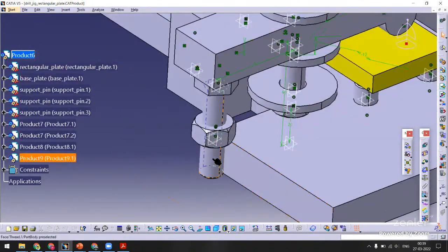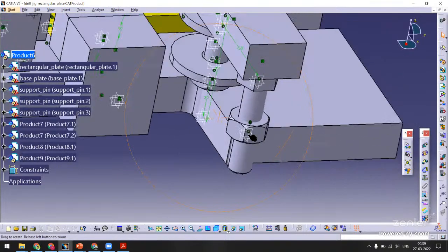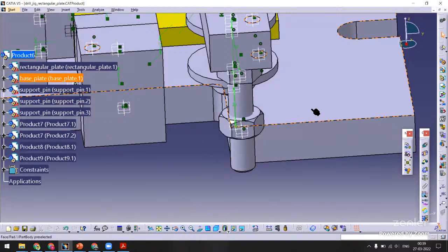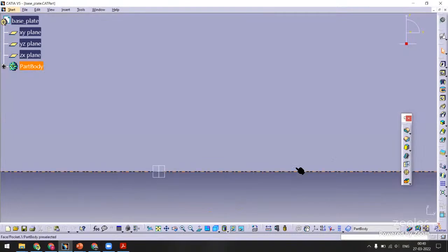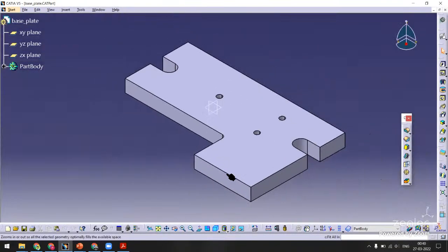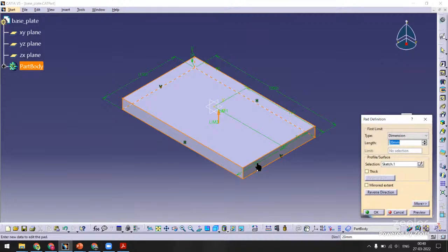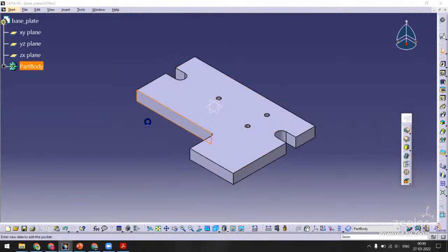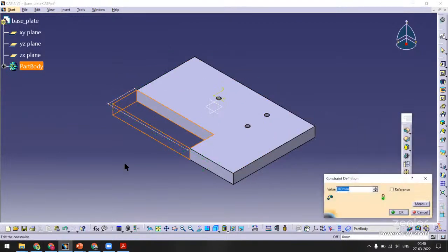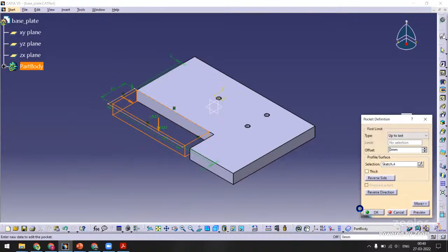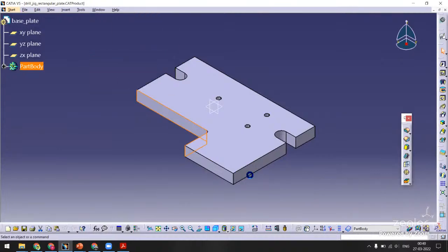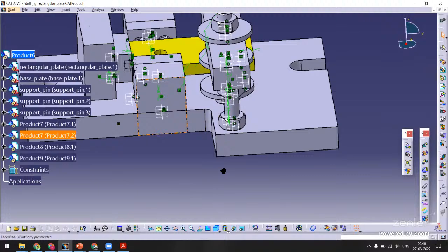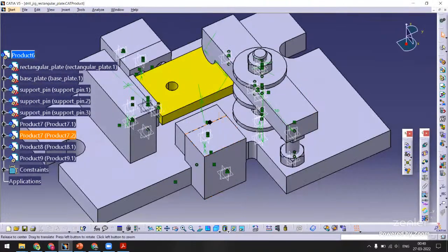Now, as you can see, the bolt has come outside. So what I would do is, I'm going to increase the size of the plate. Now you can see the advantage of this type of dimensioning. 120, I increase it by additional 20 mm. And then this, I will reduce it by another 10 mm. So maybe 150 mm. Oh, this is looking really good. Update.